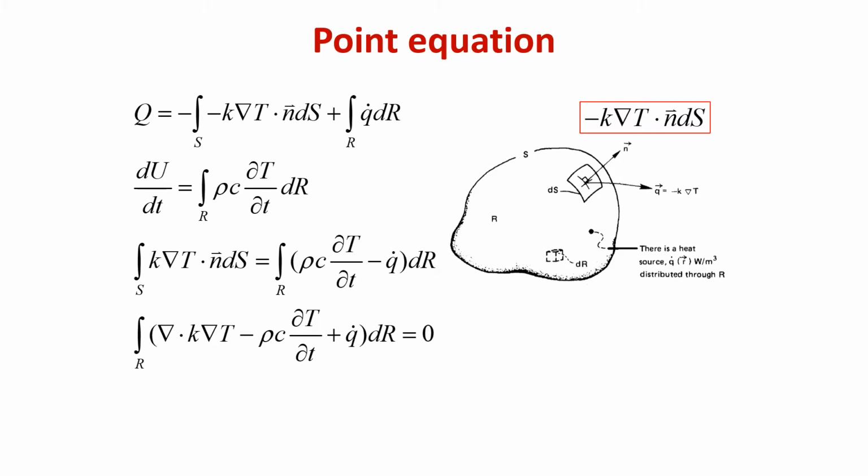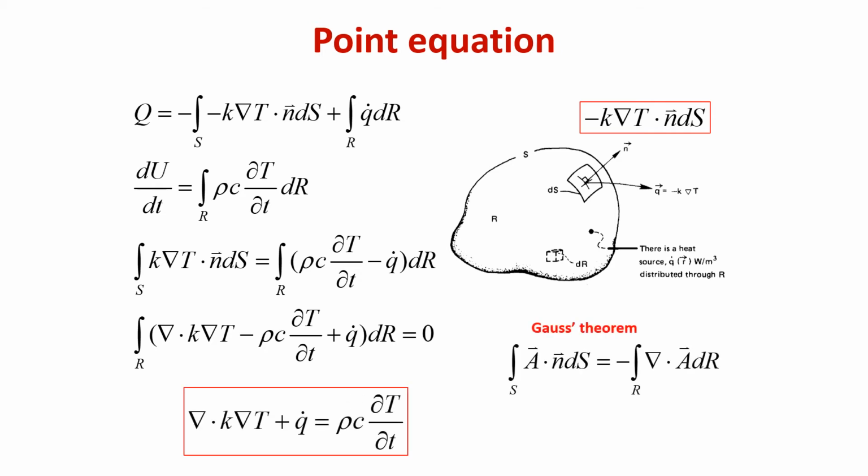The idea of pore-scale simulation is to solve the so-called point equations instead of the volume-averaged macroscopic equations over the microstructural geometry we just created. After solving these point equations, we compute the effective transport property based on the fluxes obtained through the domain. The transport equations are mainly Laplace equations such as mass diffusion, heat conduction, and electric conduction.